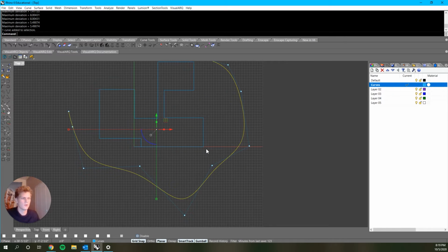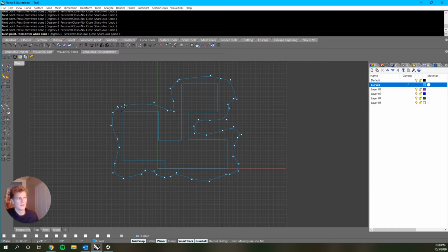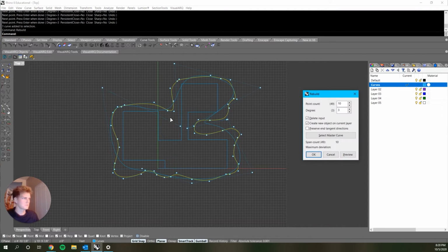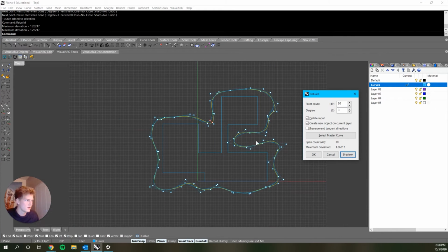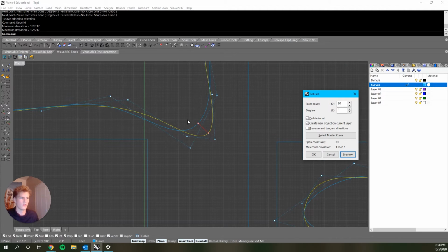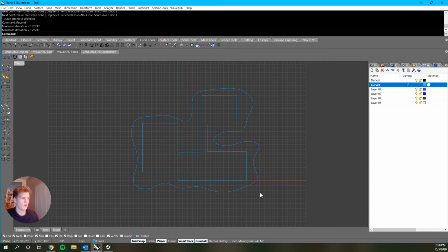And that works really well if you're doing some kind of landscaping that you want to follow, say, the geometry of a building very rigidly, but then you have an instance where it might get a little too complicated because you made too many, and you just want to simplify it a bit. So maybe you choose a new set of points there and you'll always get a highlight where the maximum differences change. So we'll hit OK there, and you'll see you can get a more fit and smooth uniform curve.